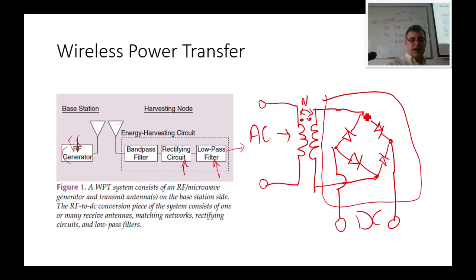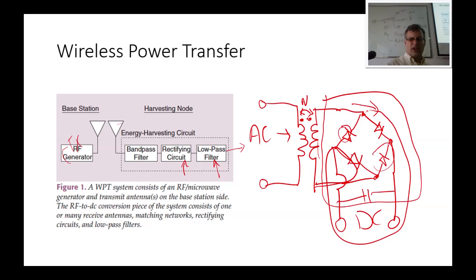Look at this. This is a bridge rectifier, and the nice thing about a bridge rectifier is it's a full wave rectifier. It's very simple to build. You usually put a capacitor here too, by the way. But really, when there's an upswing, when you've got sinusoidal current coming, and there's an upswing in the current, this diode is off, this diode is on, this diode is off, and this diode is on. So the current goes like this, and then returns through there.